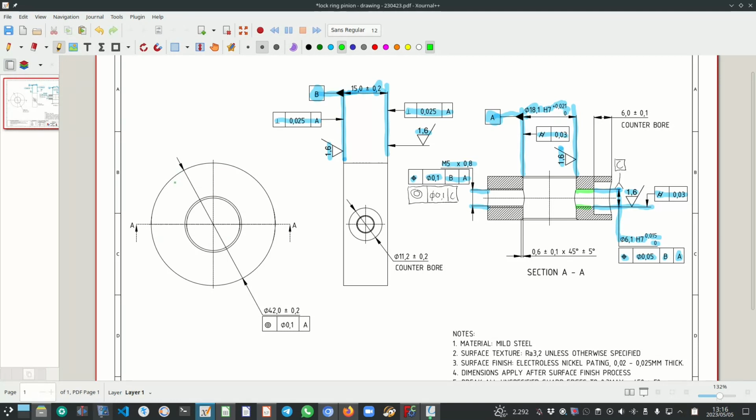He can do it anywhere. But once that hole is machined, this M5 by 0,8 needs to be concentric relative to that hole. And that's why what I've shown here is actually wrong. I wouldn't do it like this. I would rather do it like that. Okay, that's the thread.